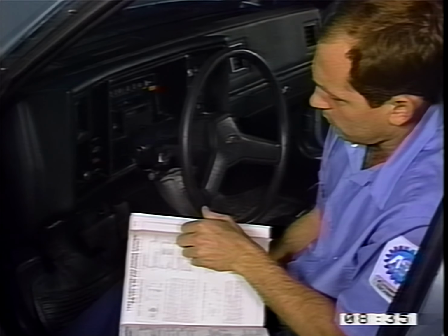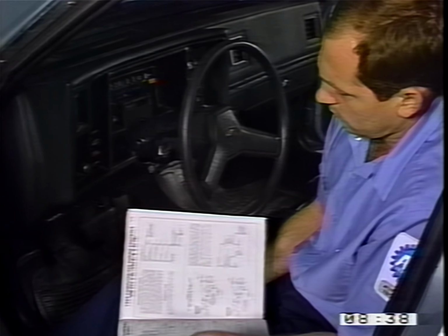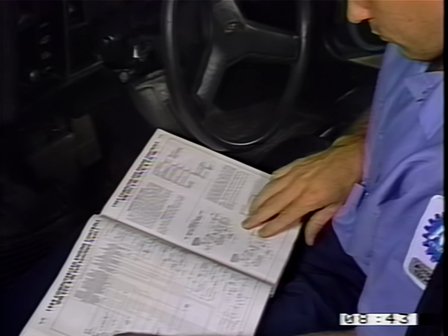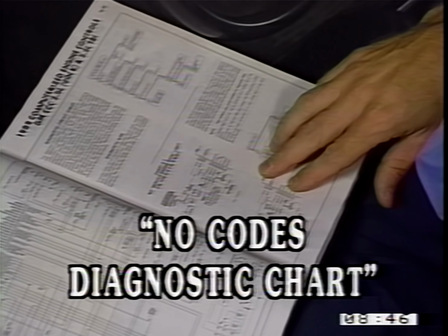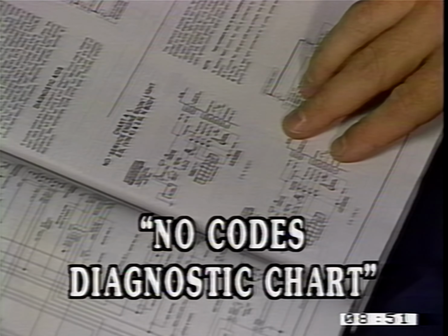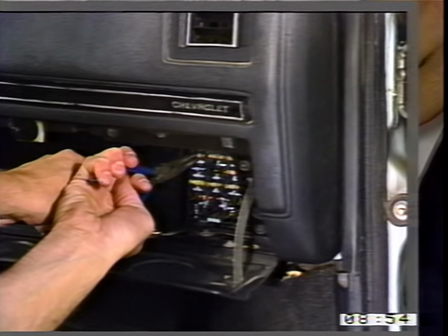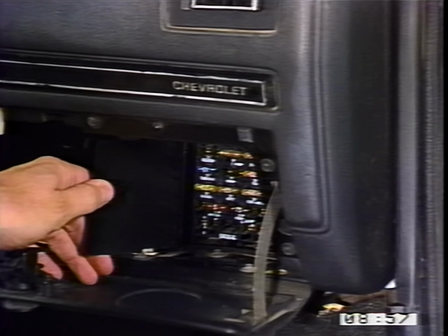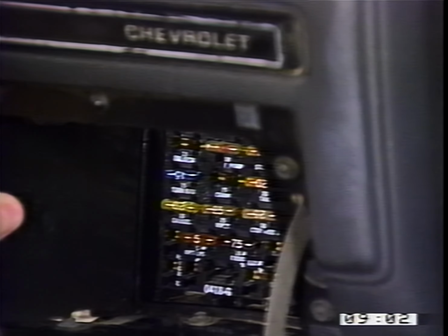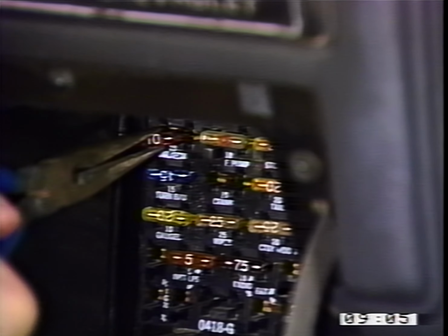All other codes are considered suspect until it can be determined why the ECM is failing to recognize the absence of a TAC reference. When it is not possible to get trouble codes to flash, go to the No Codes diagnostic chart and the lamp driver diagnostic procedures prior to any further repairs being attempted. Codes, after being recorded, should be removed from the system in order to find out if either an actual system problem exists or if there are intermittent faults being set by poor connections or outside tampering. To erase stored codes, remove the ECM's battery voltage by pulling the ECM fuse for approximately 10 seconds, then replace.